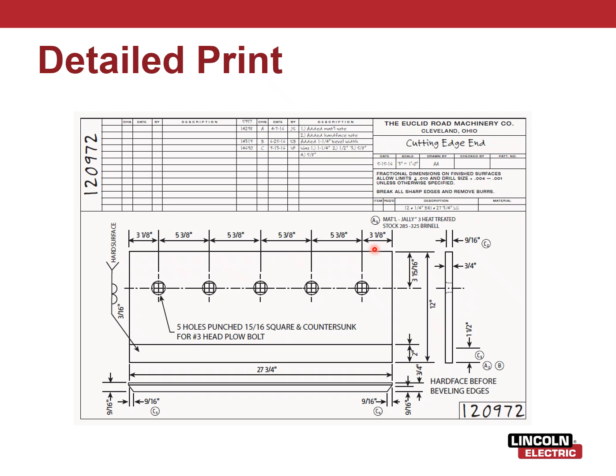And then we have the measurements, the locations of the holes, and then we have our weld symbol right here. So this is calling for a 3/16 surface weld, hard surface, all right, in this section right here. All right, and then we can also see we've got the material thickness, 9/16 in the side view right here.